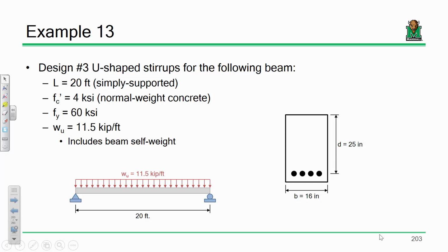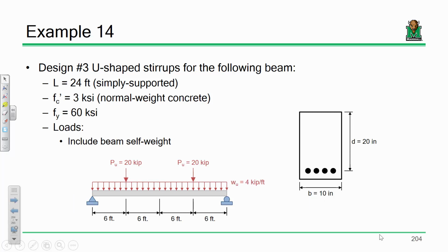-4. Why is it -4? Because that's the load, right? Remember from structural analysis, the value of the load is the slope of the shear diagram, right? So for both of these lines, the slope is -4 kips per foot. Would you agree with that?